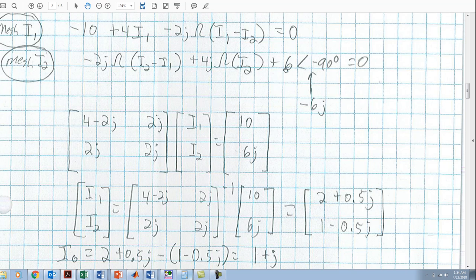And then on our right-hand side, we're going to move this phasor value over. And we can go ahead and convert that into a complex pair, knowing that for 90 degrees, the cosine is equal to 0, the sine is equal to -1, so this just really becomes -6j. We have our angle completely in the complex domain. So we have -6j right there, and when we move it over to the right-hand side, it becomes +6j.